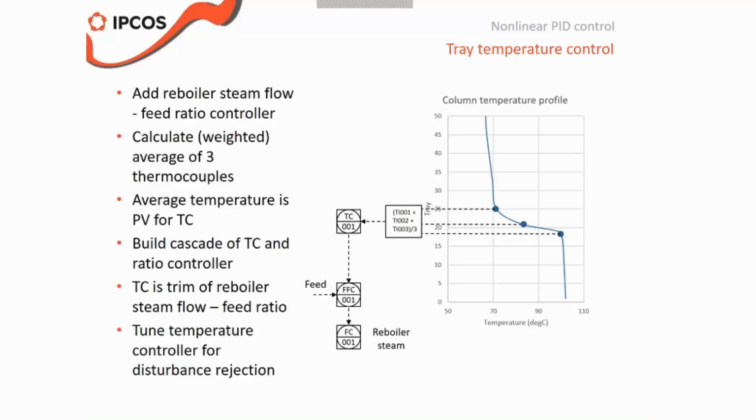And there is one regarding the pH control. For pH control, you need a characterization. So how can you find that? That's a bit of a tough question. The best way to find this is if you have a regular simulation of your plant. You do a simulation, a sensitivity analysis, or case study in HYSYS, for example, and then you will find your characterization. You could also try to extract it from plant data, which is not that easy, but if you don't have a regular simulation, then that's how you should do it.